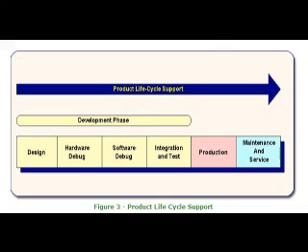While it is obvious that boundary scan based testing can be used in the production phase of a product, new developments and applications of the IEEE 1149.1 standard have enabled the use of boundary scan in many other product life cycle phases. Specifically, boundary scan technology is now applied to product design, prototype debugging and field service as depicted in Figure 3. This means the cost of the boundary scan tools can be amortized over the entire product life cycle, not just the production phase. Product life cycle support, Figure 3.